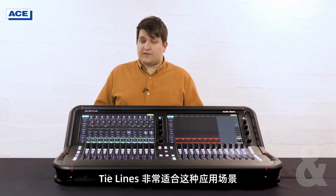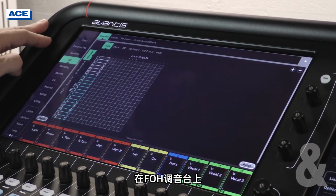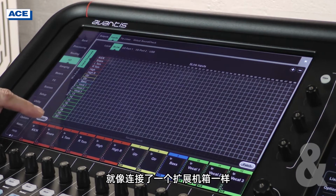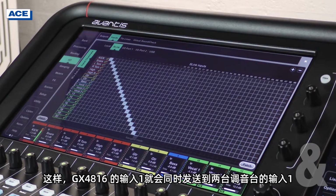Tie lines work great for this application as they bypass any processing added by the console the analog inputs are connected to. On the front of house console, we'll now need to source our inputs from the S-Link port as if it were an expander. Input 1 on the GX4816 is now routed to both consoles' input 1.